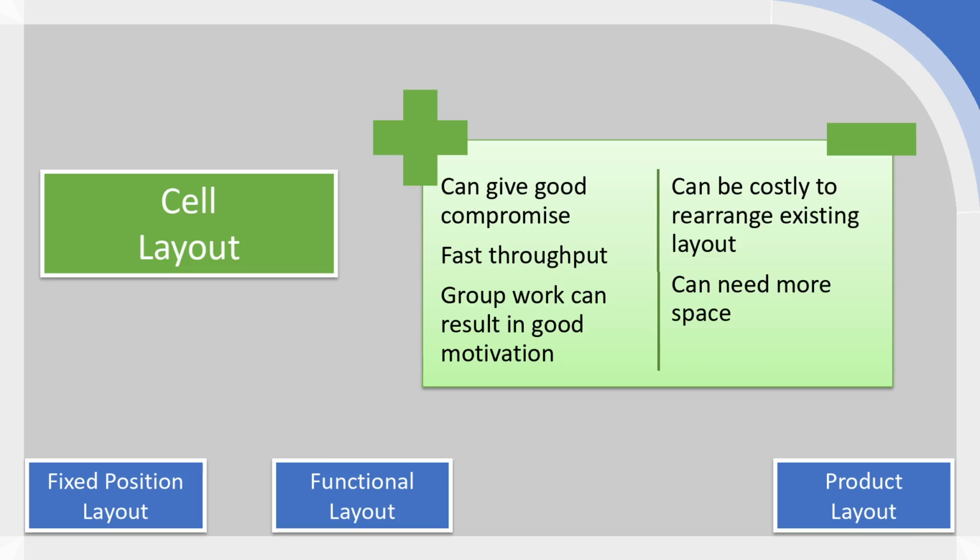So that's a significant benefit there, and it gives a good compromise between volume and variety, but you certainly can achieve higher volume than you could with the other layouts we've looked at previously. But this does require a lot of physical space. So if you were trying to arrange a layout within a factory floor to maximize space utilization, cell layouts are in some ways quite wasteful with the space. So they do require greater space and greater arrangement, and that can be fairly costly. So there are those significant drawbacks there.